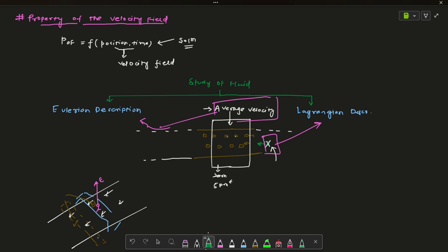So now, if he wants to measure velocity, pressure, temperature of the fluid at a particular point like this one, he will tell you u(x, y, z) at a particular point and for a particular time, or an average over some time, and he will average all the quantities. He has to say that I am focusing on that particular point and all the fluid is passing by. So he is not bothered about fluid particles. He is only bothered about the position, and all the fluid passing by.